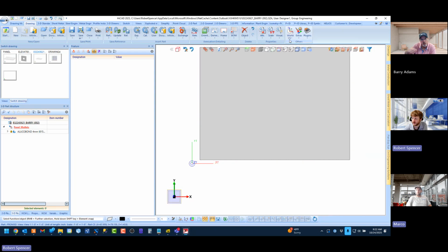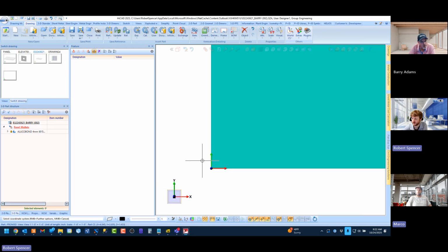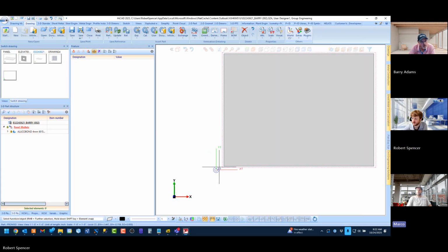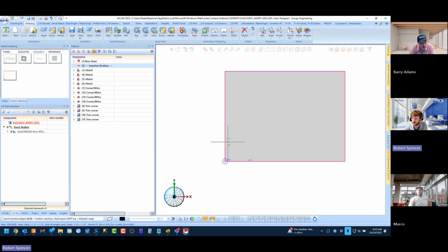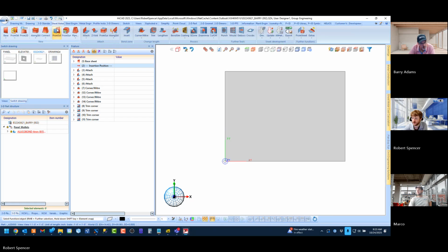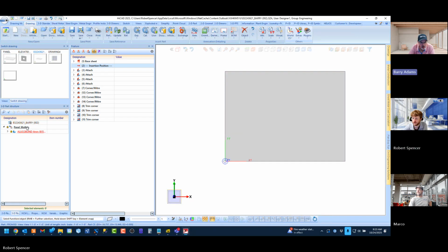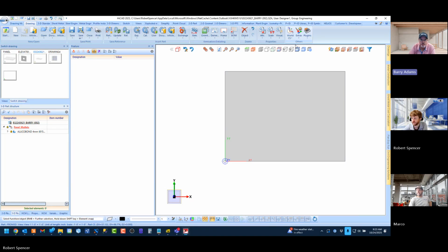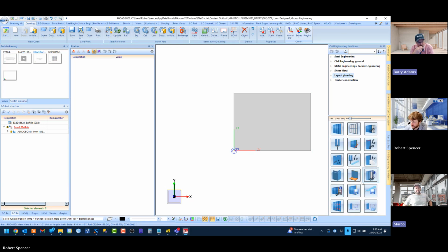And then I just said change assembly coordinate system to here. And now you kind of got to refresh it around a little bit till it updates. So let me go back to world here. And this is why you like to start everything at the 0. Correct. Okay, I understand now.